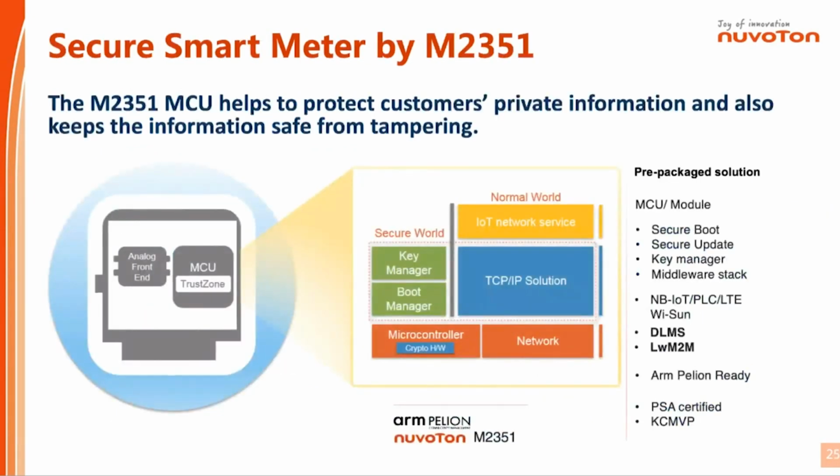This is a secure smart meter solution. It's based on Nuvoton M2351, which has an Arm v8-M TrustZone core. It supports DLMS and Lightweight M2M protocols to securely connect to the Pelion service. The boot and key managers are in the secure zone to enhance the system security.